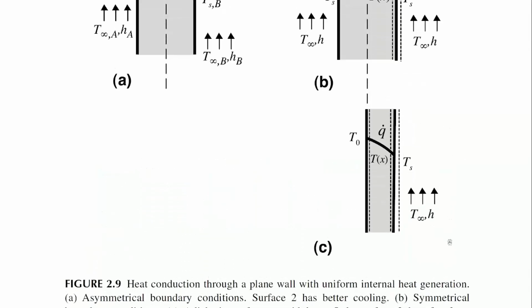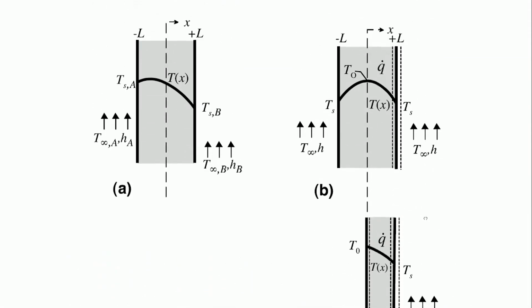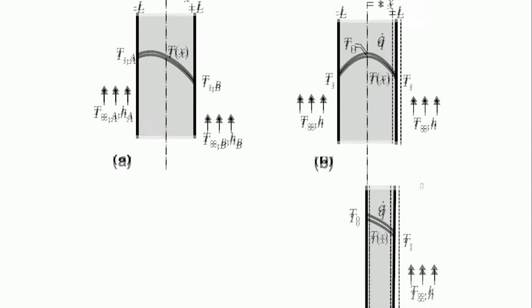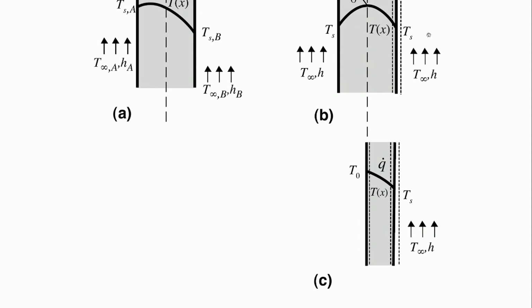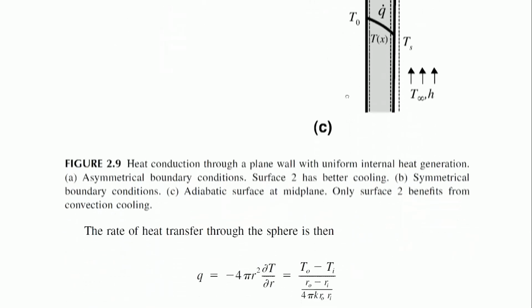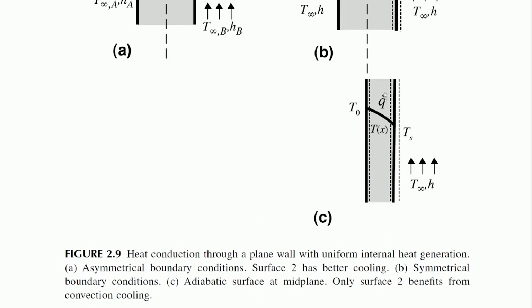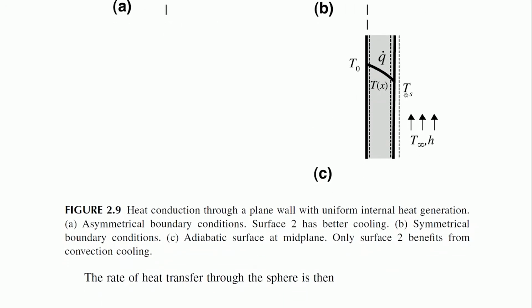You see here there are beautiful combinations of type A: asymmetrical boundary conditions, meaning one side temperature is different from the other side. Symmetrical boundary conditions, meaning you have both sides, you have seen this h_A, h_B, heat transfer coefficients on sides A and B, and in case both have similar values, and you have a temperature of the surface. So, typically a fin may be able to behave like this, and finally if something is closed on one surface, the other surface has convective heat transfer and can be open. This is typically the case with an enclosure which is trying to transfer heat across.